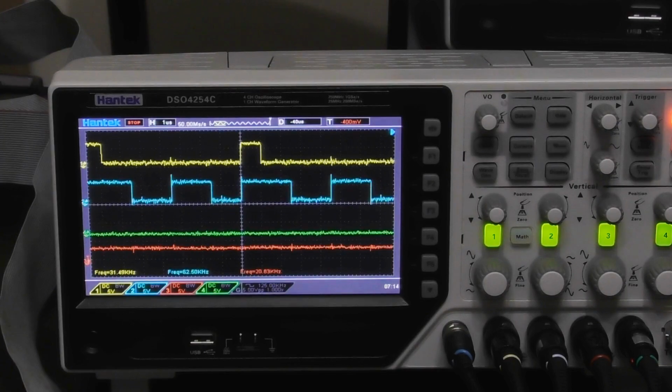What I've got in yellow here is actually the inverted data from the disk, and something I didn't mention much in the last video was that in order to get the Arduino to run stably, I actually had to invert the read data from the disk twice before feeding it into my clock synchronization circuit, and that was really to delay the clock slightly to avoid exactly this kind of problem. What I really want to do is delay it even more, and I could feed it through a couple more NOT gates. It's not ideal. Another way of delaying it more would be to add a D flip-flop and use the D flip-flop to delay the signal. That's a fairly standard way of doing it.